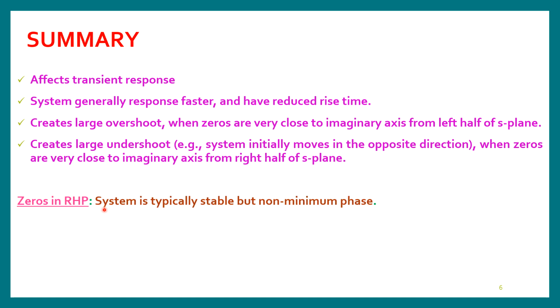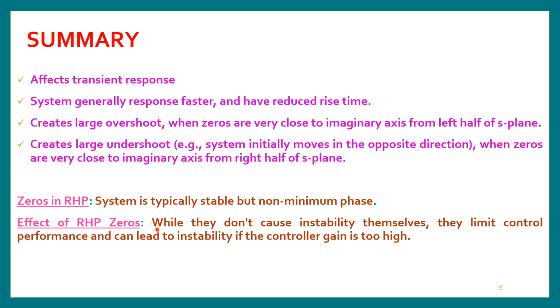When the zeros are located in the RHS of the s-plane, you can also call the system a non-minimum phase system. These added zeros will not make the system unstable, but it creates instability problems by increasing the controller gain to a very large value.